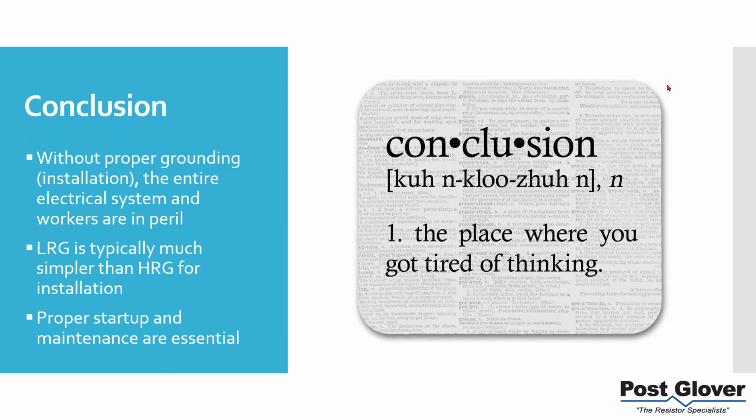Typically speaking, you're going to have a custom resistor. We probably have done it before, but it's going to be a larger resistor that meets that threshold, or goes below that threshold, I should say, so that you don't have any ignition issues. The short of it is you're going to have a much larger resistor, but you can definitely put it in a Class 1 Div 2 environment.